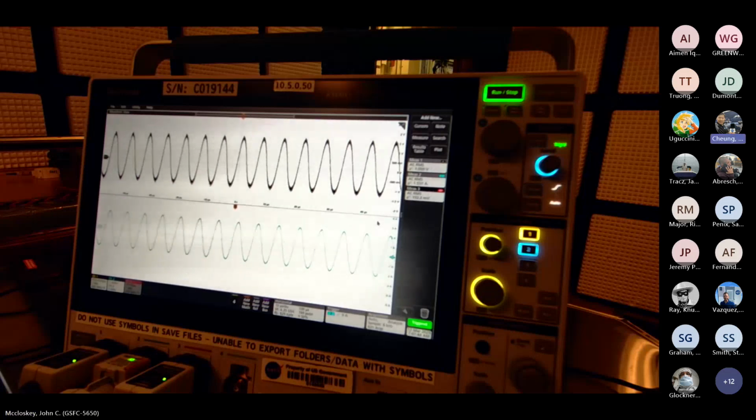One of the points I was going to make is when you hook this up to your control loop, the driver that you have in your software needs to read these values off of your scope. So you need a driver that's matched up to the scope you're using.